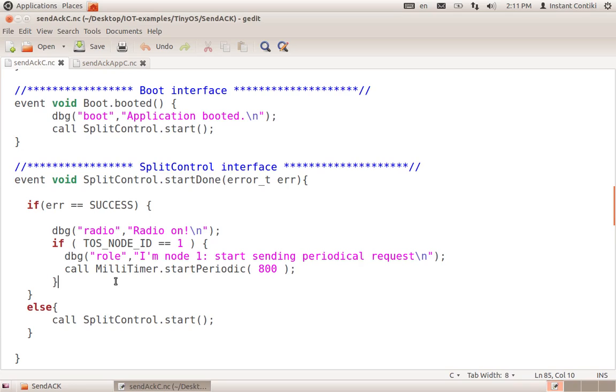In TinyOS, it's not like this, it's a little bit different. So the simulations that you can set up are basically constrained to run the same source code. So all nodes in a simulation will run the same source code. That means that if you want different sensors to do different stuff, you have to specify it directly in the source code. Okay?